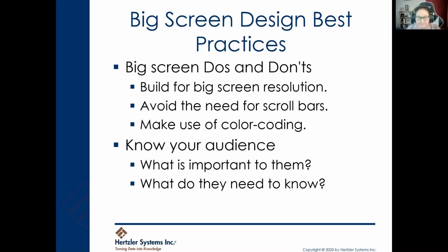Okay. Finally, and this is probably kind of obvious, but I think it does help to repeat it, you need to know your audience. What do they need to know? What's important? When we start at the beginning, the reason to be putting data on the big screen display is to give the people that are seeing that screen the information that they need to take the action that they need to take. So if you're going to put something on the big screen, make sure that it's what the operators need to know, otherwise it's just going to be a distraction at best.